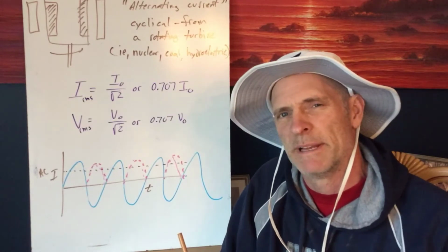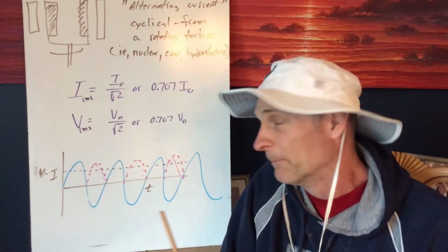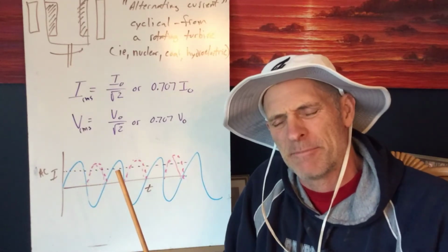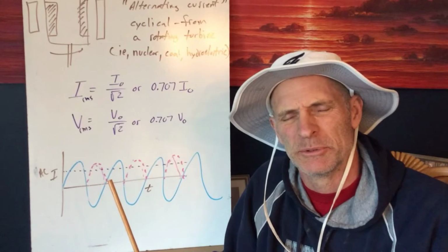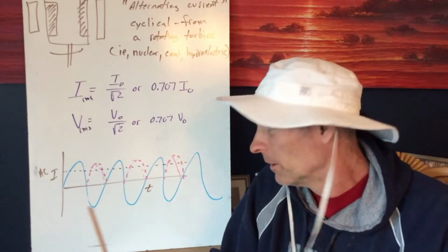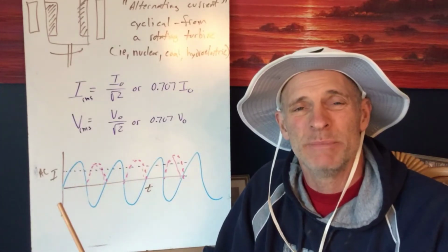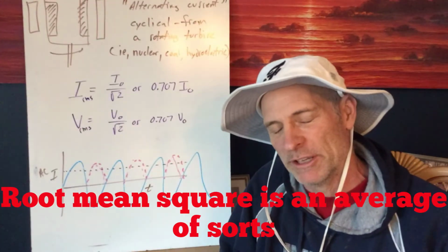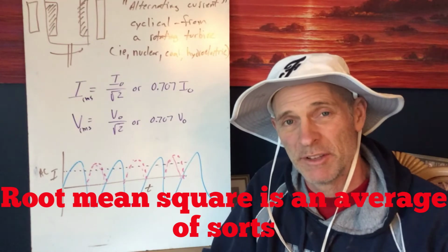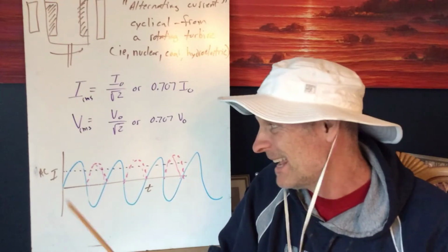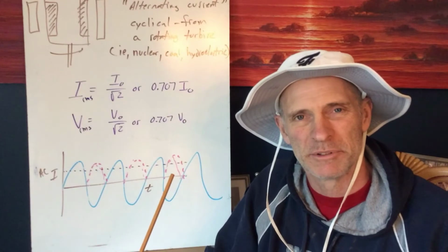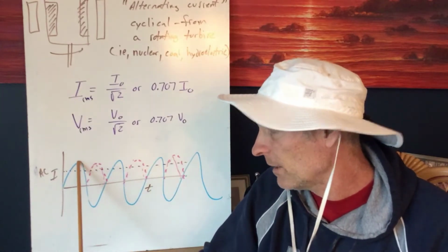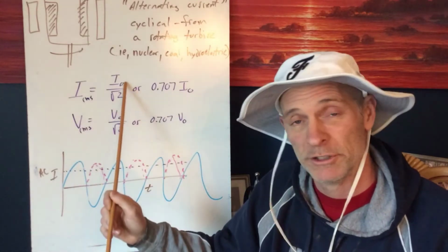Okay, guys, I've just made a couple of adjustments so you can see a little bit better. The average, doing some fancy mathematical manipulation, see Mr. Aziz or Mr. Avicic for more details, we get what's called a root mean square. This is the approximate average of the power that you would receive, or the current you would receive, by taking the middle of all these humps. It's not actually the middle. It's more like 70%.